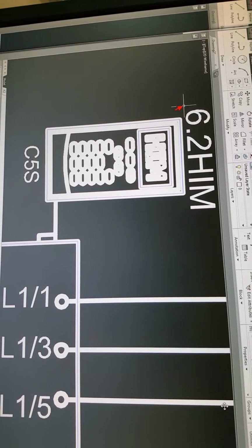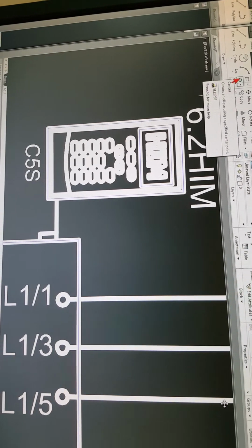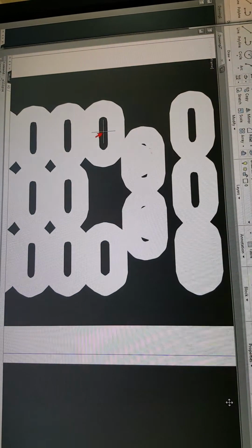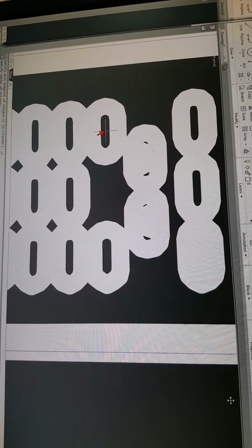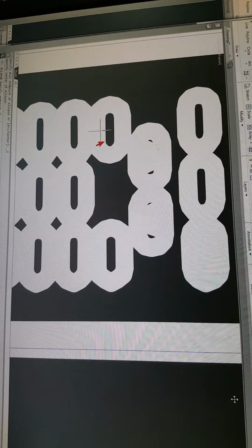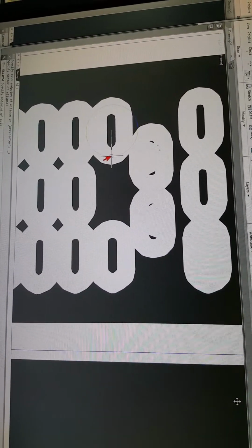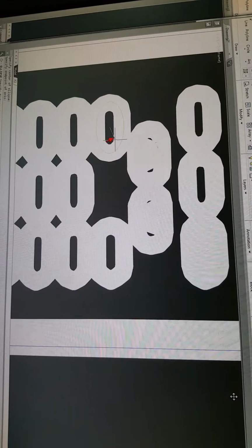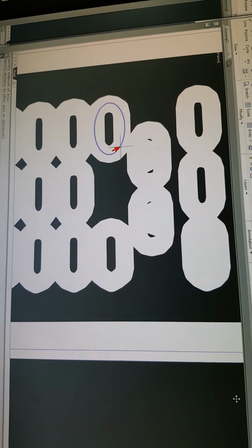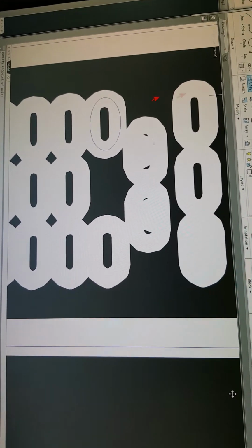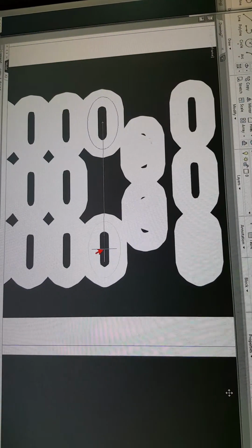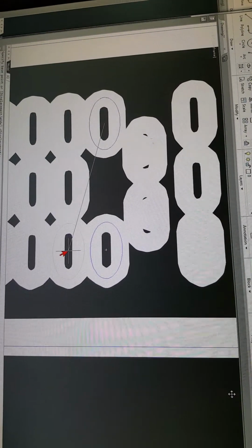And then there's an ellipse command. Ellipse. What does it want? It wants the center of the ellipse. Okay, the center is probably here. And what's the specify endpoint of axis? Well, the endpoint is probably here. And now you can adjust it the way you want it. And there it is. Now copy it. Copy from where? From center. And just drop it in these other centers. How's that?